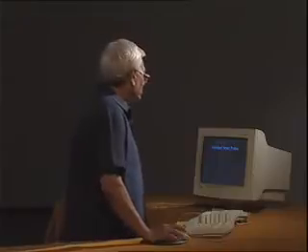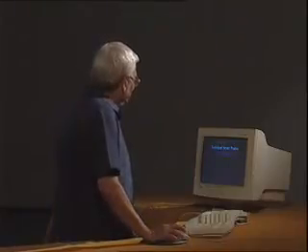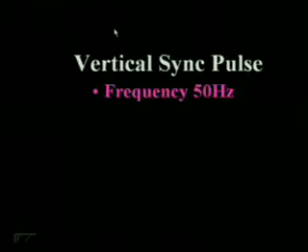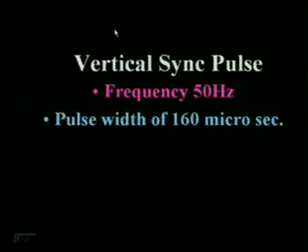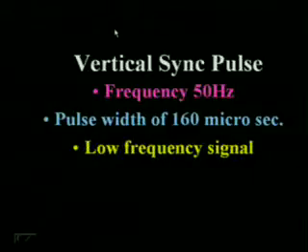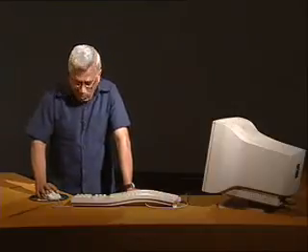What about the vertical sync pulse? The frequency of the vertical sync pulse is 50 hertz. Pulse width is 160 microsecond and it is known as a low frequency signal. So, there is a big difference between horizontal and vertical frequencies in terms of pulse width.